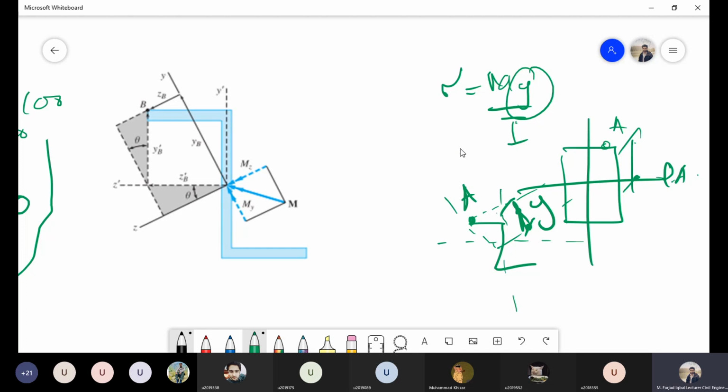Now, let's suppose I have to calculate the stress. One way is that usually we are provided with the horizontal and vertical distances. For example, I will be provided with this length that is 10, this length maybe 11, and this length as 10. If I have to calculate the stress at point A, first I have to know what the y distance is, and then I will transform this y distance onto the inclined axis. Now this particular work gets complex, and we may need to look for some alternate method, or there are some alternative equations.